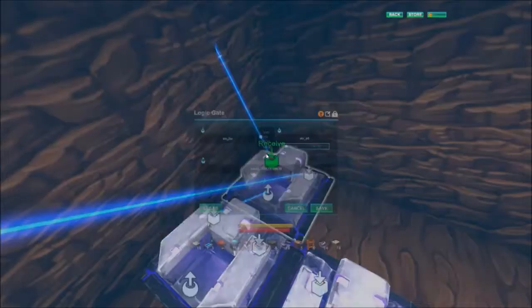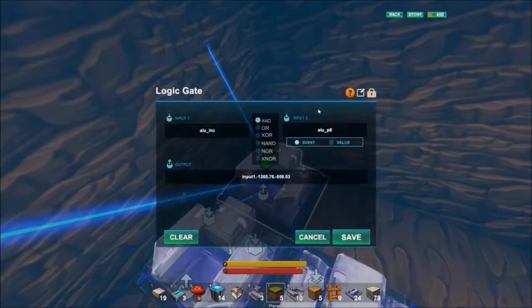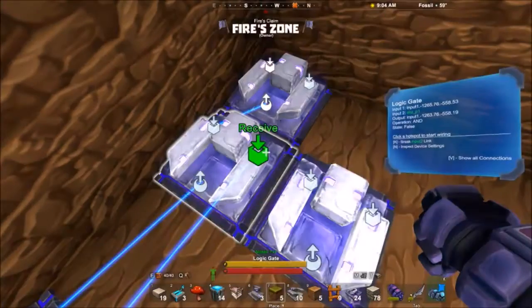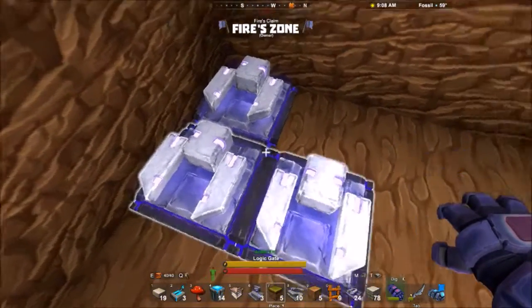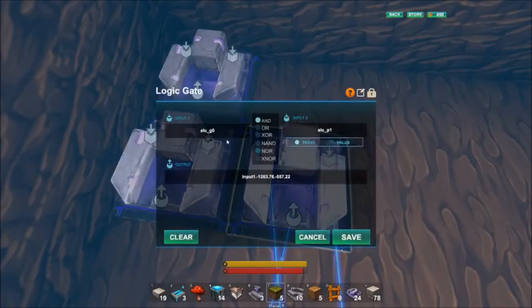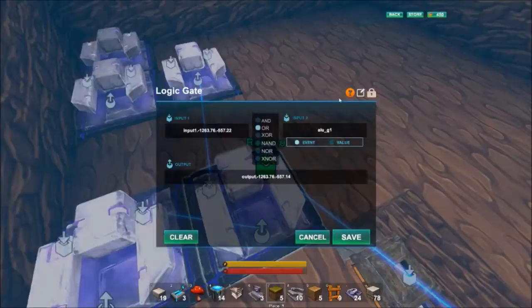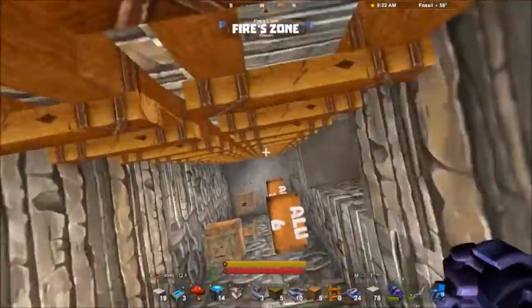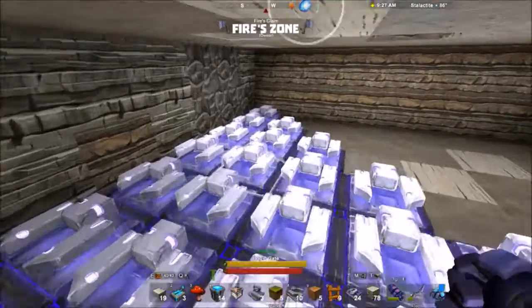So the first one is always going to be the increment, but on bit 2 it no longer needs to be propagated just by bit 0, because bit 1 also needs to be propagating the signal. So the first option will be that you get the increment, bit 0 propagates the signal, and bit 1 propagates the signal. The second option will be that bit 0 generates the signal and bit 1 propagates the signal. And the third option will be that bit 1 generates the signal. And this is going to keep adding extras until it goes to the last one. So I'm not going to go through every single one, but let's have fun with this one a little bit.